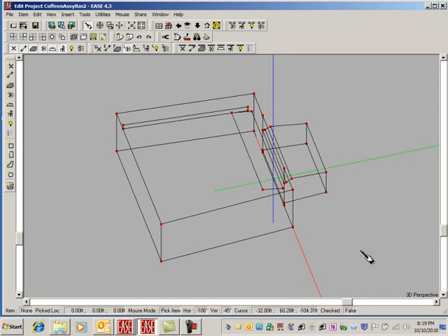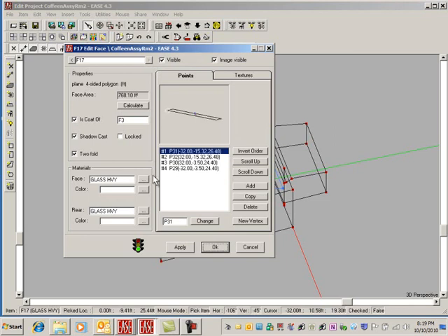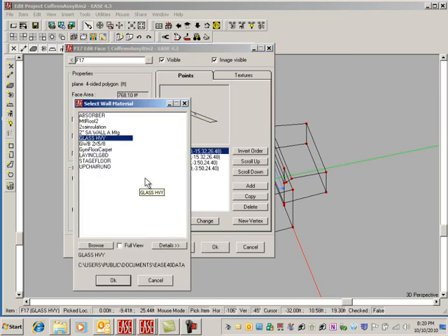So this is important. If we do an F4 here, we go to Properties, and the front side is going to be, I think, gypsum board. That's the top surface, bottom surface, 2 layers of gypboard. Well, that's the front side in this case, gypsum board. And the rear side, the blue side, is going to be 2-inch glass fiber insulation. We do that sometimes to keep sound from actually sort of rolling out into the room from above the ceiling. In this case, that's what we want it to do. So we say OK, and we can say OK.